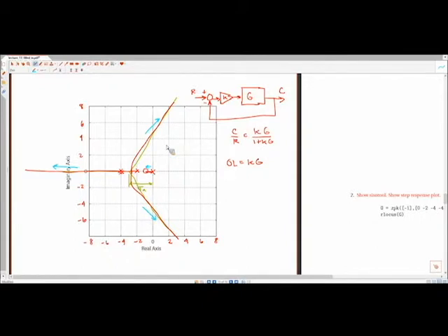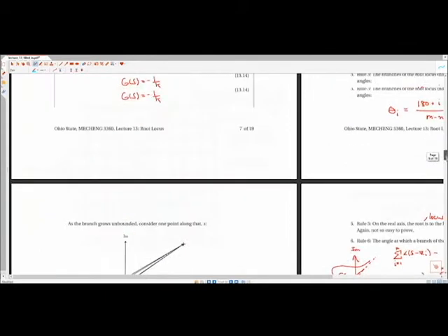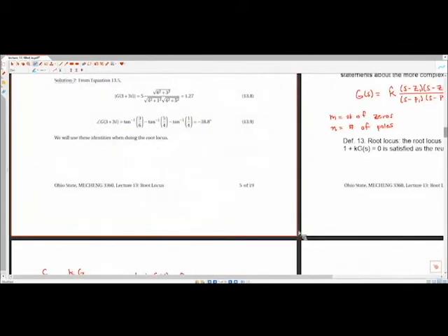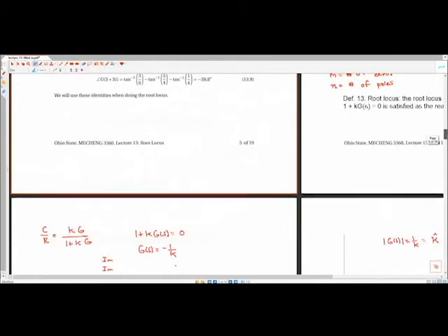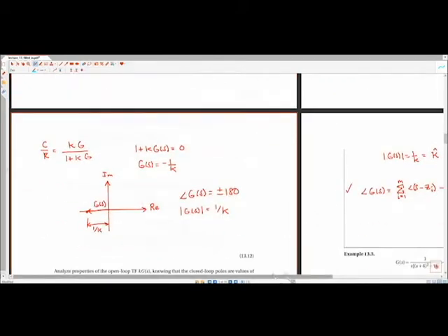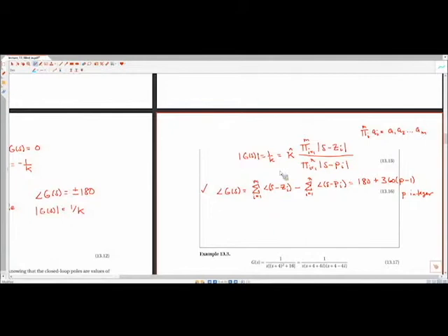So the way in which we can do this, we can use the same rules that dictate the root locus. As a reminder, the two rules that define our root locus are this angle criteria, which is basically how we built out everything for applying the root locus, and now this gain criteria, which allows us to understand and find some unknown k for closed loop positions S.